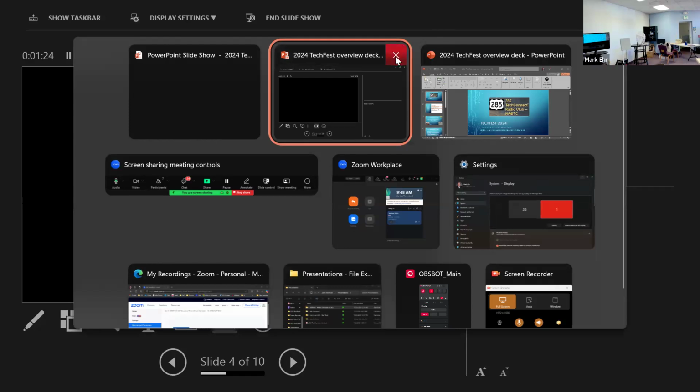Yeah, so it actually runs both simultaneously. The radio has two channels, one horizontal and one vertical. On the other side, it figures out which channel is which. So if it was exactly 90 degrees, it could figure it out, or with no rotation, it could figure it out. But we try to keep the paths as clean as we can so that you don't have a lot of rotational problems. If you get into the Fresnel zone, all bets are off.